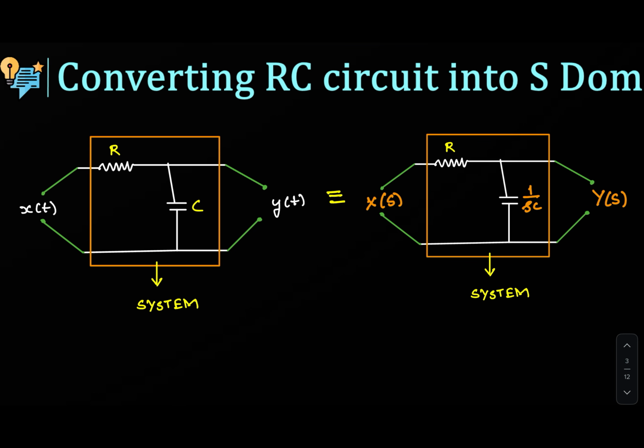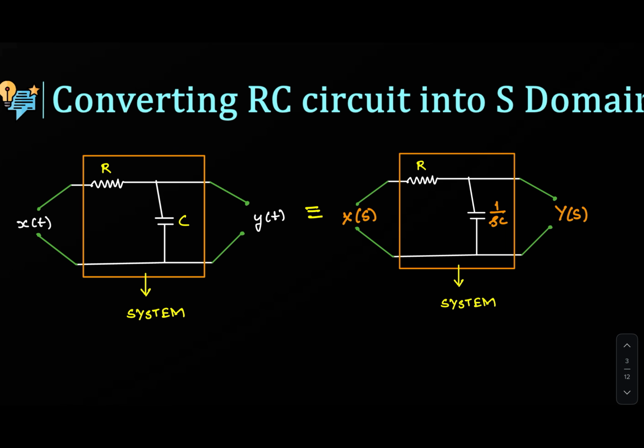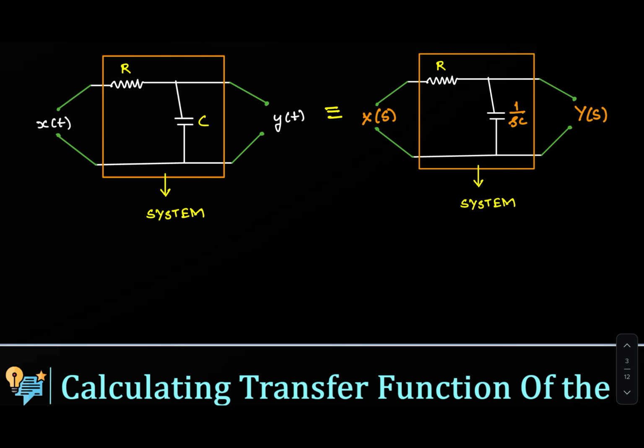So this is converting the RC circuit into an S domain signal. So we have converted this time domain circuit into an S domain circuit.